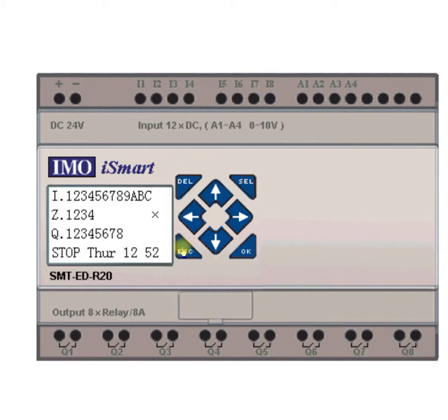And this is sort of like the window between the two programs, the PLC program and our program that runs the loaders. Across the top you can see the inputs, 1, 2, and 3 would be station 1, 2, and 3, the material switch coming in. So if you see that highlighted, it's going to tell you that it's calling for material. And then below you have your 8 outputs, and they'll be highlighted when the relays are telling those devices to activate.